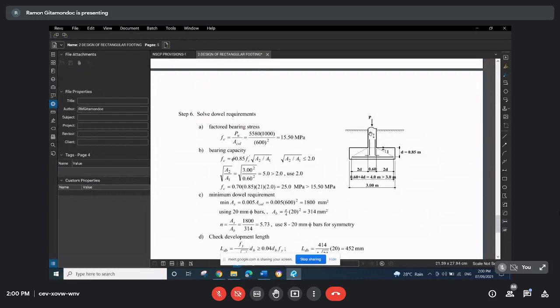In purely axially loaded columns, it's not absolutely required. Just embed all the column rebars, because what you need to do is simply to assure adequate load transfer from the column to the footing. And that is by bearing at the contact area. If that is insufficient, then you provide the dowel bars. They will act as compression bars to also help in transmitting the downward column load to the footing.